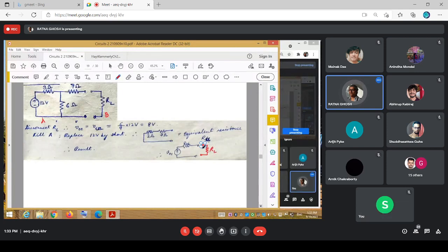So this was the B part, as if that would be connected to just an effective open circuit voltage source with an effective series resistance. That is all this needs to know, an equivalent source representation. So the whole objective of Thevenin is to look back from this load resistance and find out this effective source, or the equivalent source. So in this particular case, you've got this one.